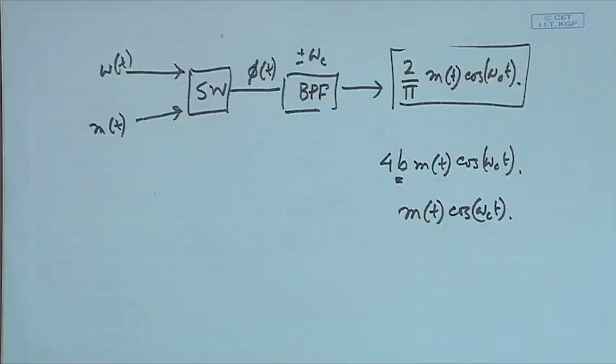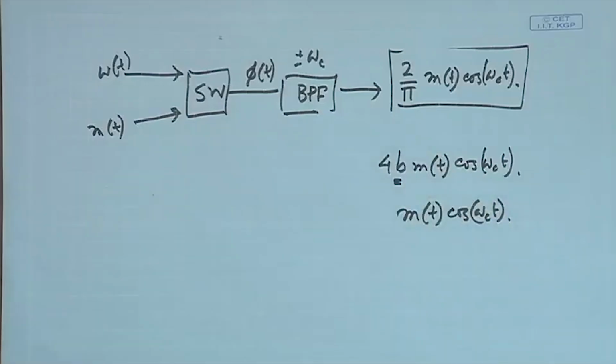Okay. The nonlinear one is also quite alright, as long as my B is not very small. With a nonlinear device, the biasing is very sensitive. If the coefficient becomes too small, especially the quadratic coefficient, then again this will be very low, and most of my power will go into the linear part, which is anyway getting cancelled out. Okay. So, that is also very important.